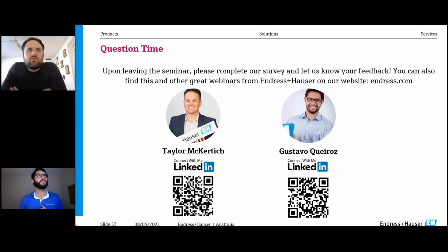I think the first question is for me actually. Online moisture measurements, can they be applied to filter cakes? Are they sensitive to the moisture that's bound chemically? So the answer is yes. Because it's TDR technology, it's measuring the moisture within the entire field of measurement. That includes any moisture inside the capillaries, or inherent moisture, as we call it in the mining industry. So you'll be able to measure that inclusive in the TDR device, which is good.